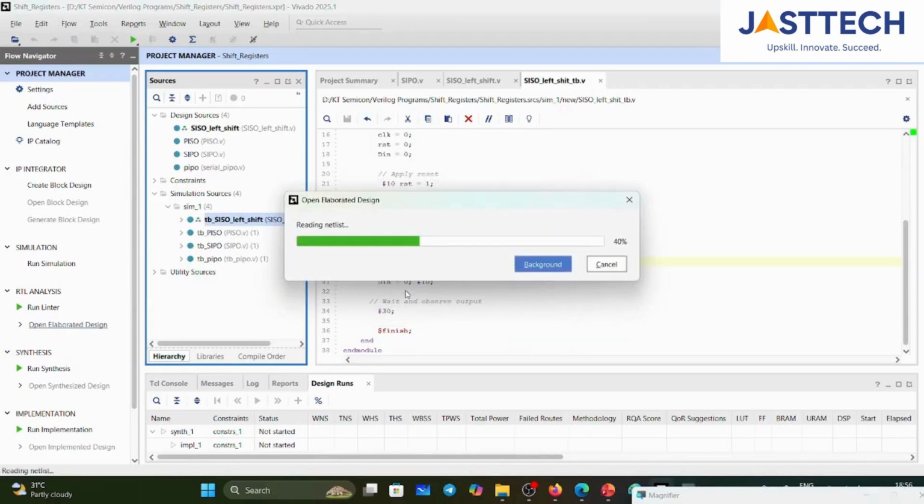You can see we will design the shift registers by using D flip flops. So 4-bit shift registers means 4 D flip flops are required. Okay, I hope you have the idea about digital; in digital we see the shift registers. Mostly counters we already discussed, that counters are designed by using T flip flop and JK flip flop, operated in toggle mode.